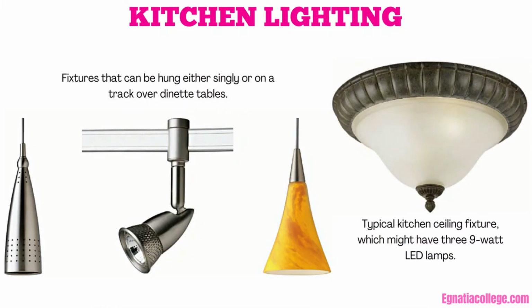Kitchen lighting. The general lighting for the kitchen is provided by 2 track lights controlled by 3-way switches located next to the doorway leading to the living room and at the rear entrance. All fixtures must be Canadian Standards Association (CSA) approved.